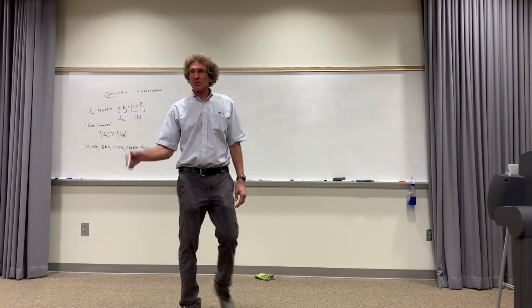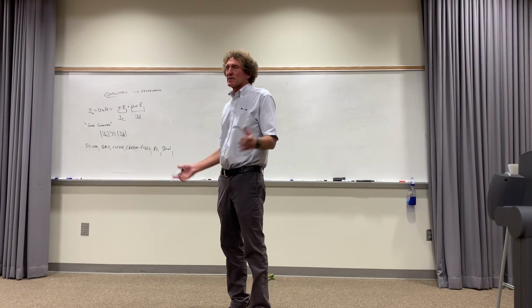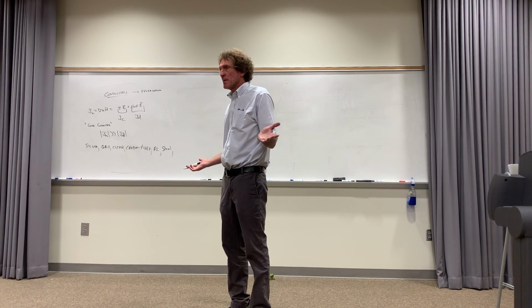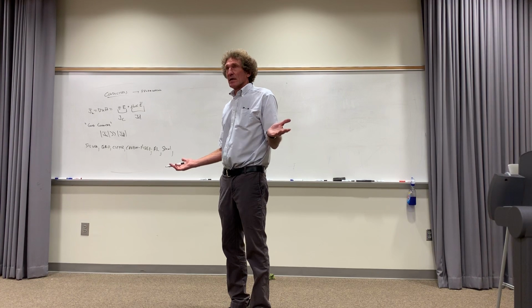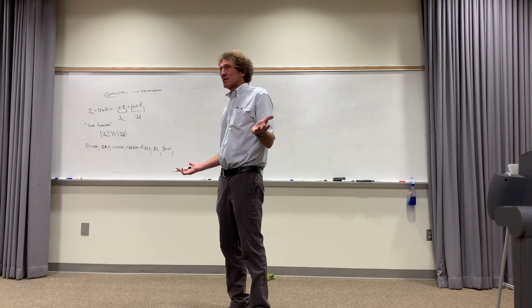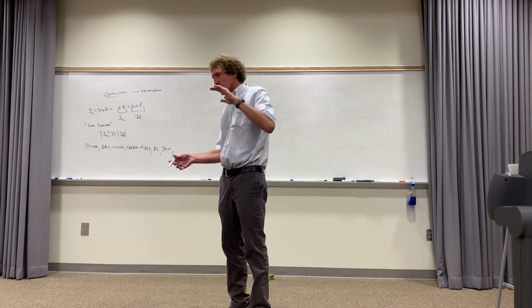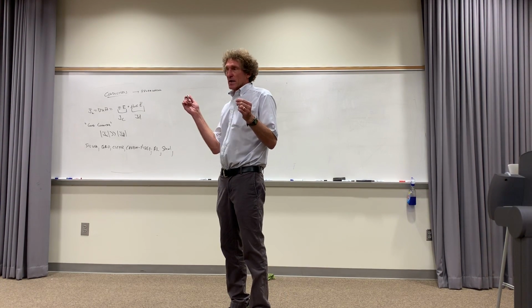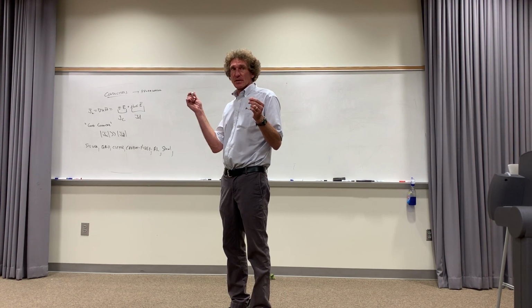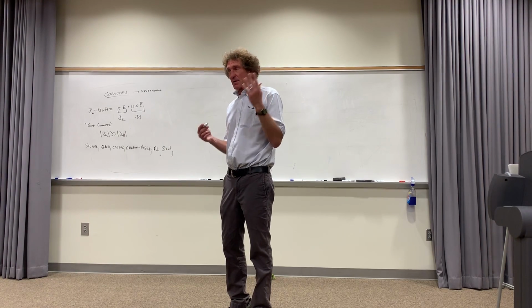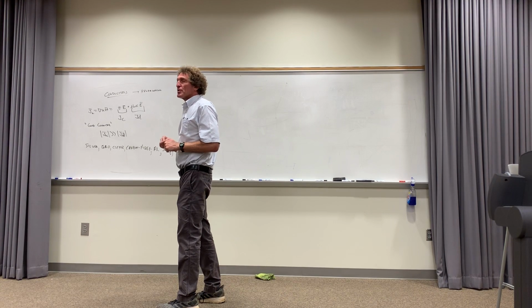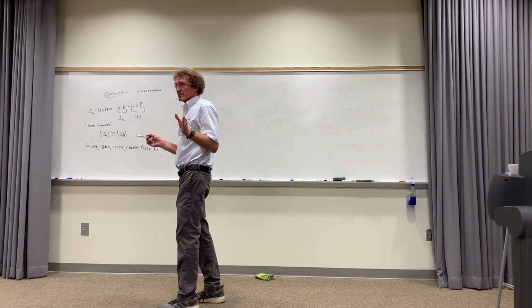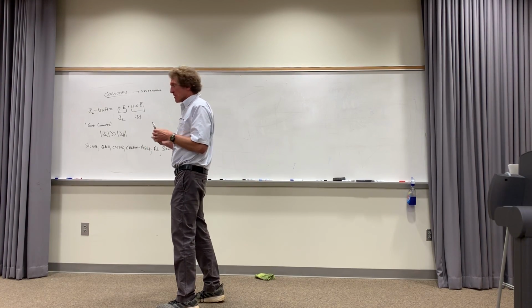You could go to brass and all the other things and even talk about alloys, but metals in general are good conductors. And if you talk about graphite, graphite has a long bond one way, short bond the other way. In one direction, that's a short bond, it's a very good conductor, in the other way, it's not so good. But graphite's a conductor. There's a lot of different things that are pretty good conductors at almost all frequencies we use. Gold is probably the best. Gold and silver and copper are the most common.